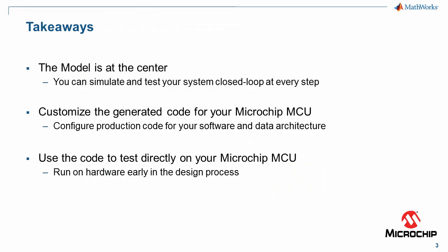Here you see the key takeaways of this webinar session. In our proposed workflow, the model is at the center. This means that the whole algorithm design is done in Simulink. Any changes in the development process have to be reflected in the model. Out of the model, we generate customized code for Microchip MCUs. And the algorithms which we designed in Simulink are directly tested on the Microchip MCU with real hardware using rapid prototyping.